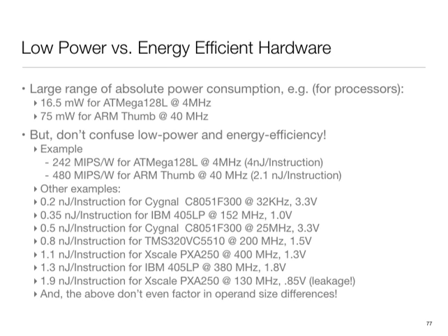So I may have two processors, one of which is indeed lower power, that is, when I'm running it at maximum speed, it consumes less power than the other one. But if it consumes 2 times less power but takes 3 times longer, then it takes more energy. That is something to be aware of. What you often see is that there is a tension between these two. There are processors which are very low power, which consume very low energy per instruction.